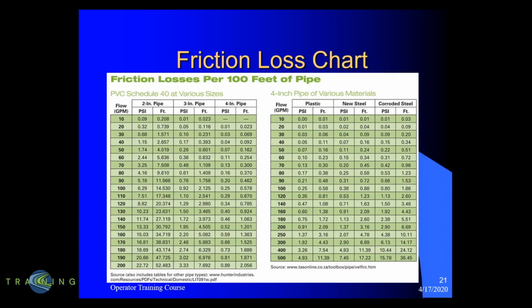But that's really important. A lot of times we see problems, especially with chlorinators, because people try to run too small of a line from their chlorinator ejector over to their injection point. And if that line is very long and your pipe size is very small, you can get a lot of back pressure, which means that you're not going to get the right amount of differential pressure to pull a vacuum in your ejector so that you can open up those regulators to get your chlorine flowing. So this is important information when we're sizing, but I just wanted to give you some understanding of how we look at that, so that you can see what difference it makes for choosing the pipe with the amount of flow that you have.